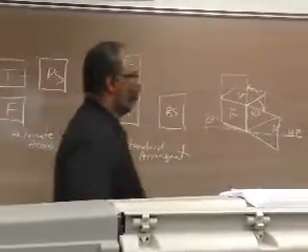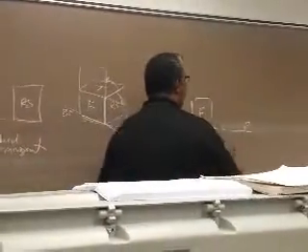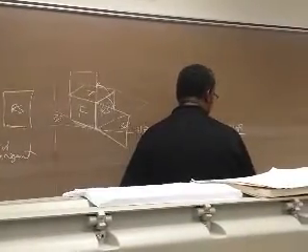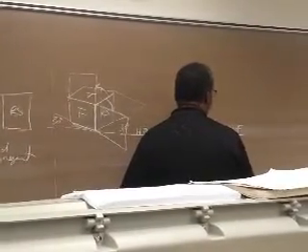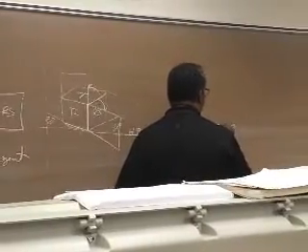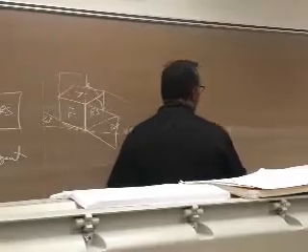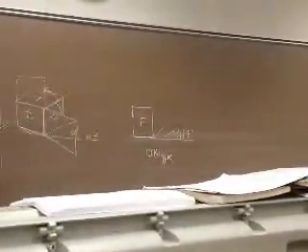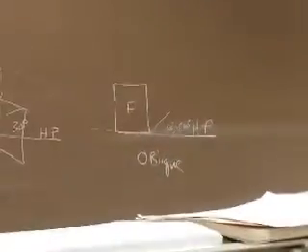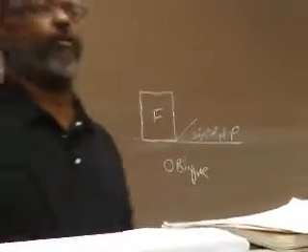So you're looking at it perpendicular to your surface. And then to show depth, you go back at an angle, and your standard angles are 30, 45, or 60 degrees. Those are your standard angles to match your equipment. 30, 45, your 30-degree triangle and your 45-degree triangle.